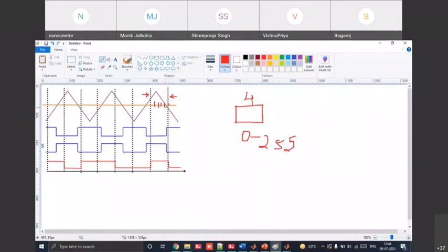Do you see how, using the help of RT events, we are actually increasing the accuracy of the PWM generation? Since we have the capability of capturing up to 255 events, in an indirect or direct way, I can say that the PWM pulses which we are generating from the RT events have 255 times higher accuracy than the Simulink one.